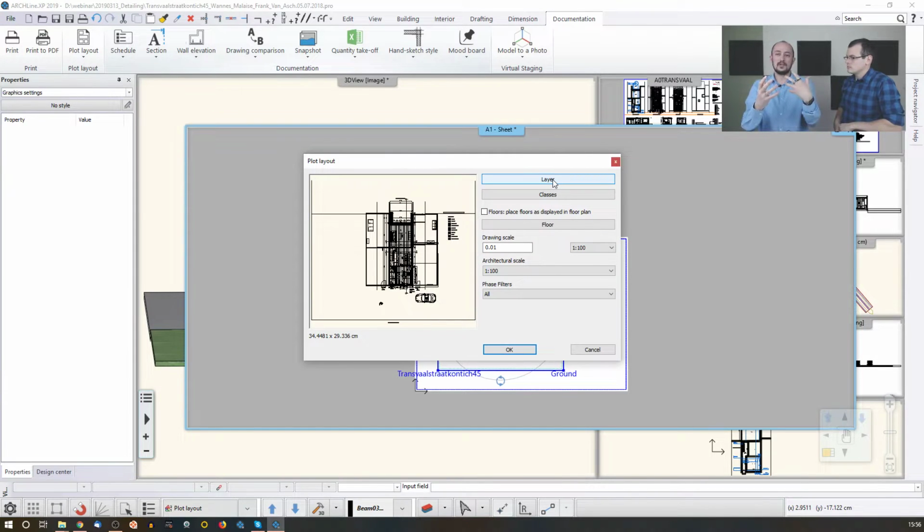This way, inserting the same drawing a second time, I can see two different combinations of the same drawing. Just imagine there is the building plan, the electrical plan, the furnishing plan, and the tiling plan, all coming together from the same 2D drawing by handling the layer combinations. Perfect. So this is how it goes, yes?